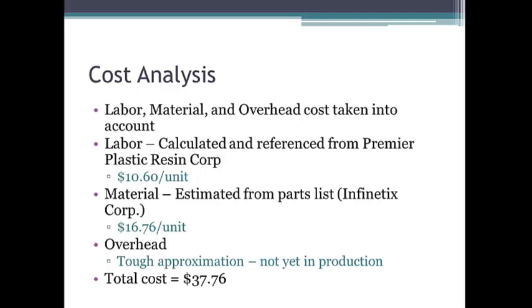Next, for machine runtime at $30 an hour at a 36-second average cycle time at 100 units an hour, with an operator cost of $15 an hour for 10 hours, this comes out to 45 cents per unit for the 1,000 units of production. Next, there's the cost of the mold. For the injection molder, to make the exterior shell, which comes out to $60 an hour at 100 hours for a total of $6,000 or $6 a unit.